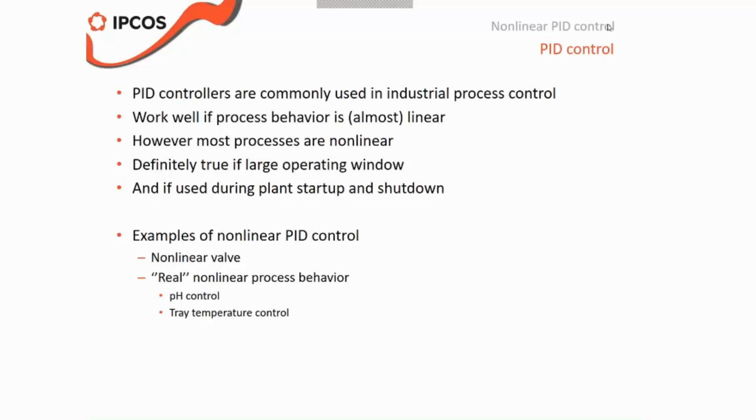And that definitely helps the operators, because if there is an upset, then that requires all the attention from the operators, and they have to focus on the process really hard. And if this disturbance just propagates to different areas of the plant, then that means more work for the operators, which eventually could lead to off-spec product, or even worse, a plant shutdown. So once again, it's very important to have good performance of the PID controllers in the DCS.